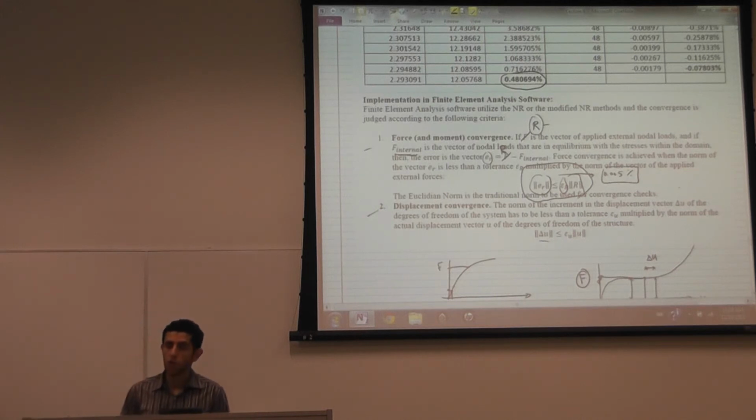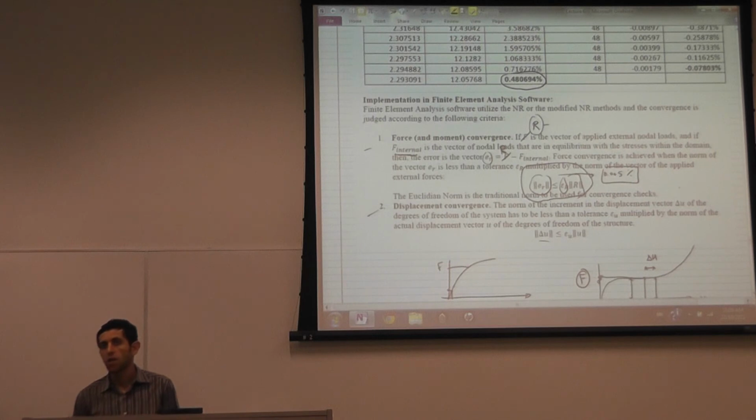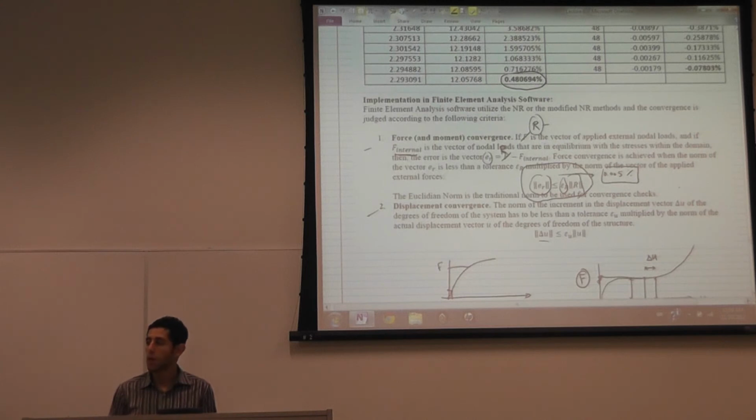So you really need to understand this when you're doing a nonlinear problem. In Abaqus, I get an email from a student telling me, the software says too many attempts, I've done too many attempts and I've not reached a solution. What should I do? I can't give you an answer to this because every problem is different. You have to read the message. You have to understand the physics of the problem to know why the software is doing too many increments without achieving a solution.